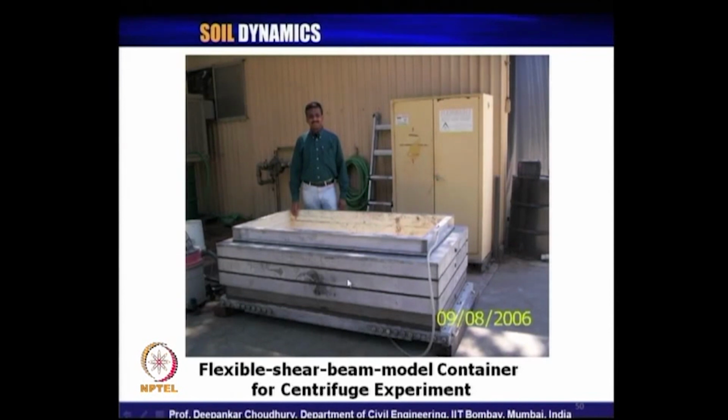All these individual layers are hinged between these 2 layers, so that when axial shaking is applied, one layer can move with respect to the other layer, similar to the behavior of your soil media. That is, when waves are propagating within this soil model, and it is shaken at the bottom, different layers vibrate at different mode shapes.